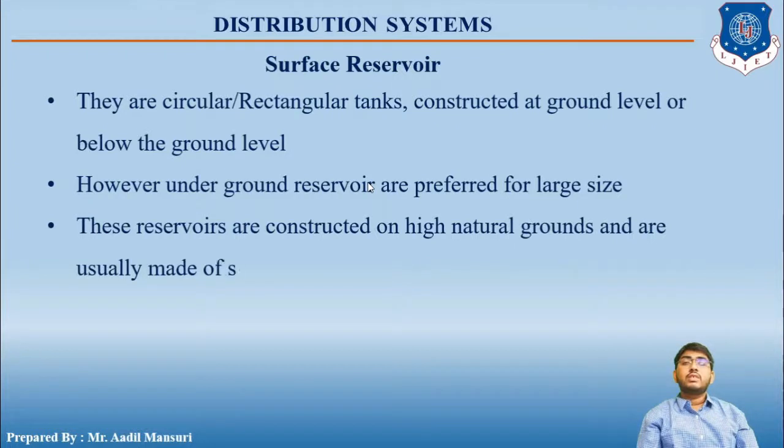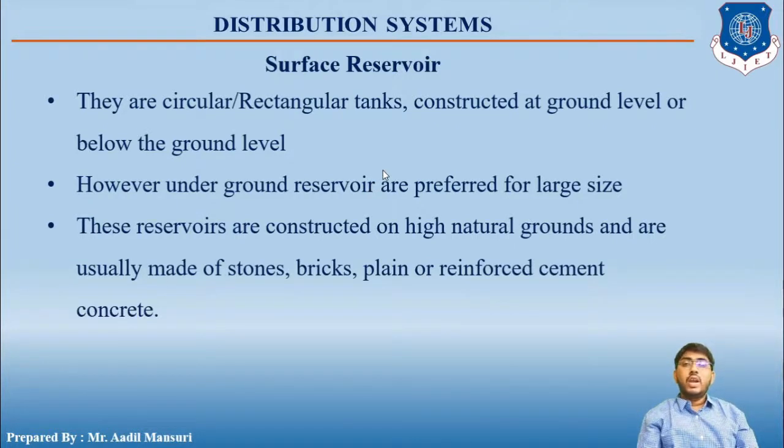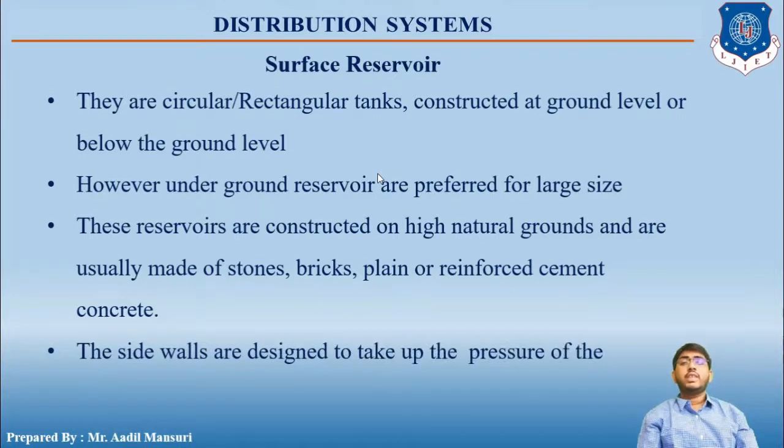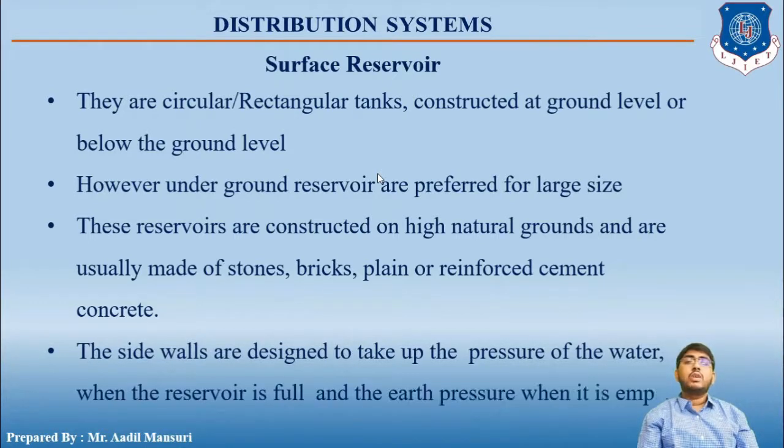These reservoirs are constructed on high natural grounds and are usually made of stones, bricks, plain or reinforced cement concrete. Next is that the side walls are designed to take up the pressure of the water when the reservoir is full and the earth pressure when the reservoir is empty. Okay, why? Because when the water will be there inside the tank, then the water will be exerting pressure, and when there will be no water, then the wall will be surrounded on the outer side by the earth, so earth pressure will be acting when the reservoir is empty.